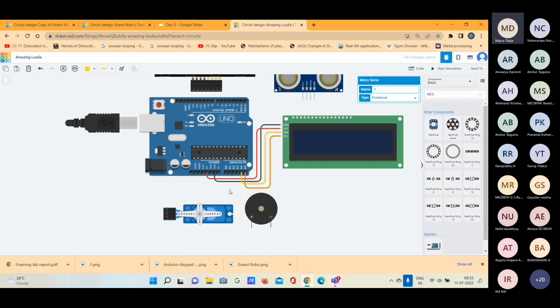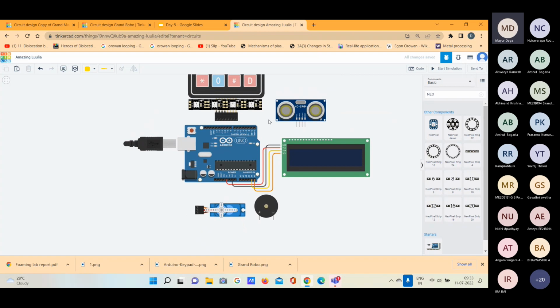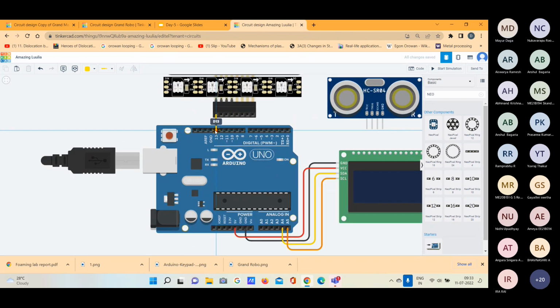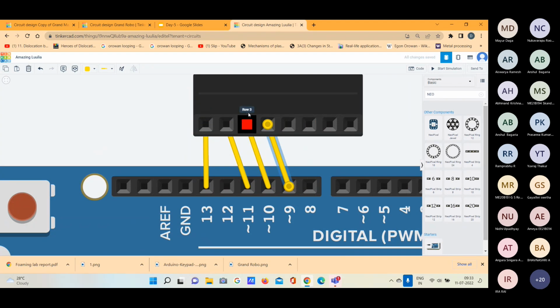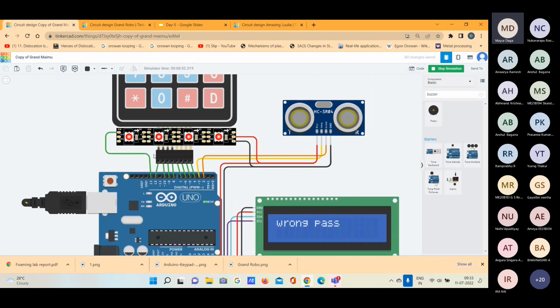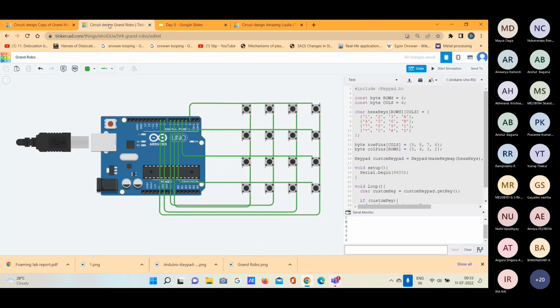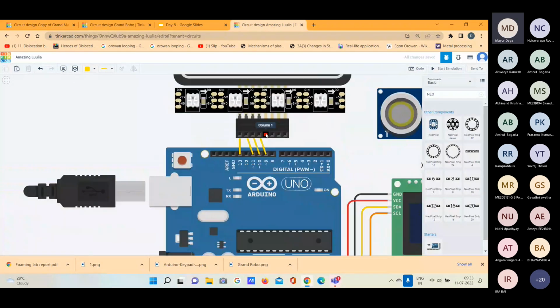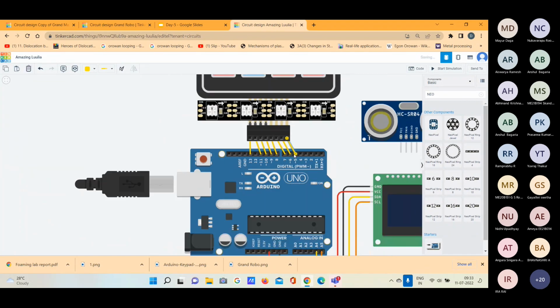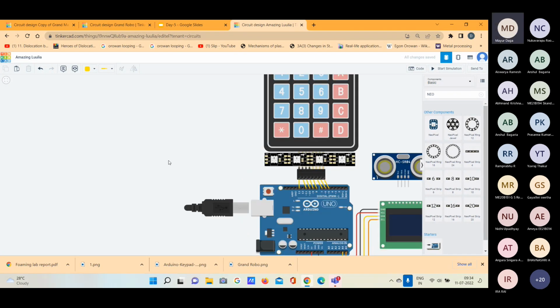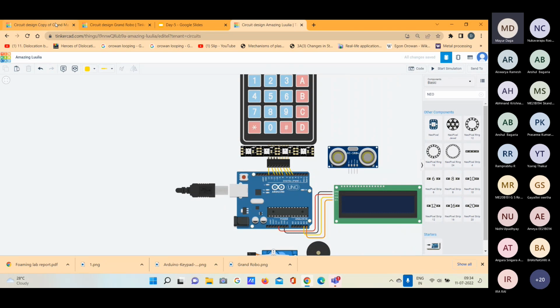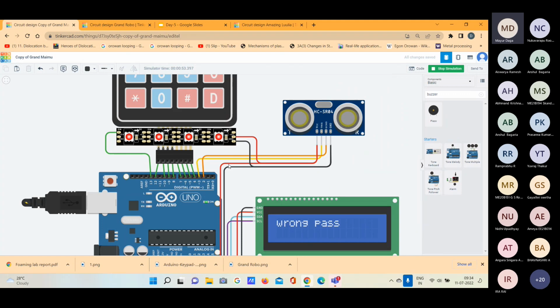And what I'll do is I'll set this keypad matrix here. So these are the row pins of the keypad matrix you can see here. I'll connect this to the column pins. So these are the rows of the keypad matrix, and these are the columns. And we'll connect this NeoPixel to, let's check what we did here. NeoPixel is connected to pin 13.